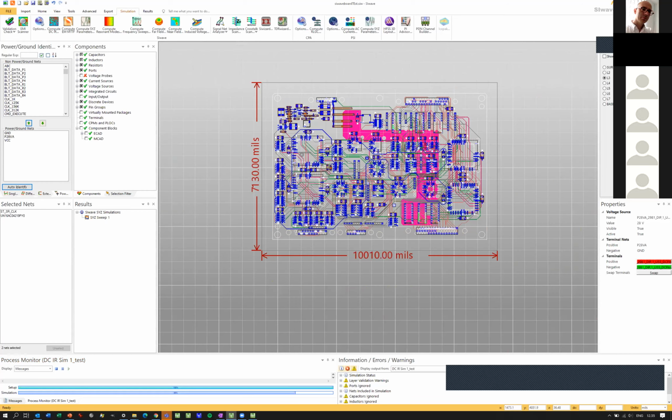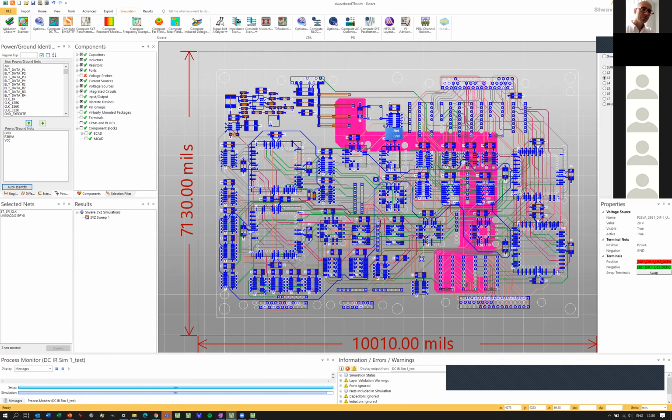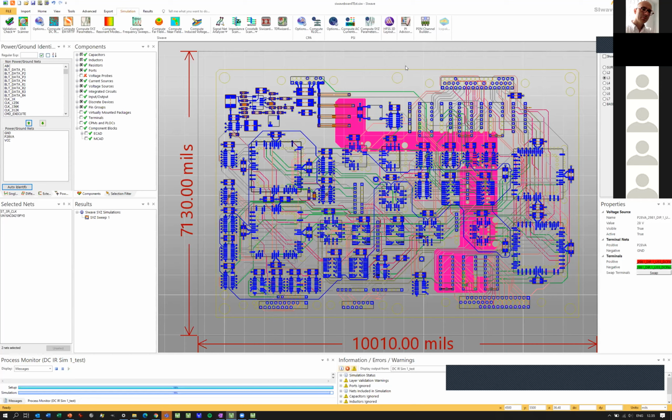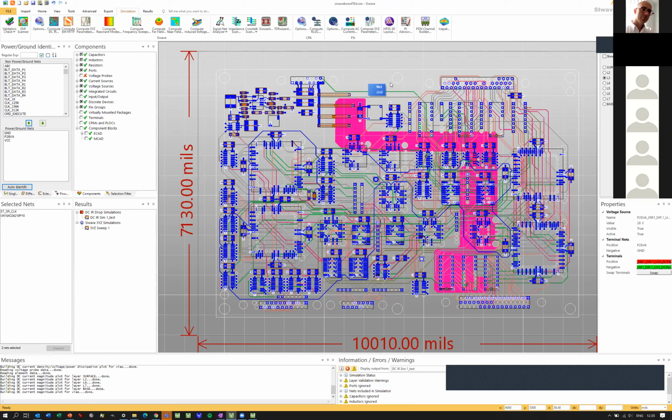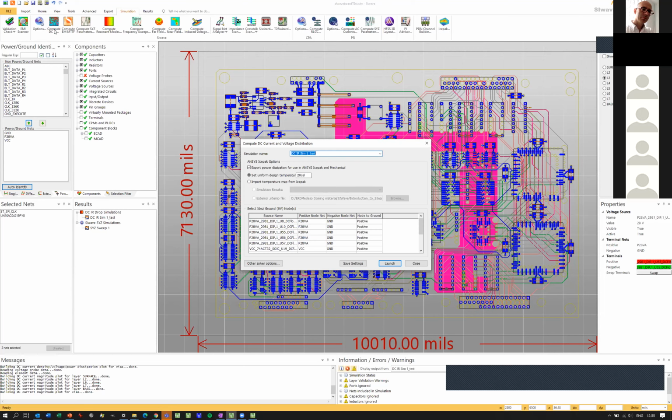So it's including both the IC power sources and the traces and circuit board heating. So it's a combination of power component consumption and the circuit board resistive heating. So it's really accurate. So we can predict the circuit board temperatures in, let's say, ±2 degrees, even ±1 degree accuracy, at least in most cases. Of course, if it's really complex, lots of high components, uneven power distribution inside of the component, the results are not ideal, but close enough many times.